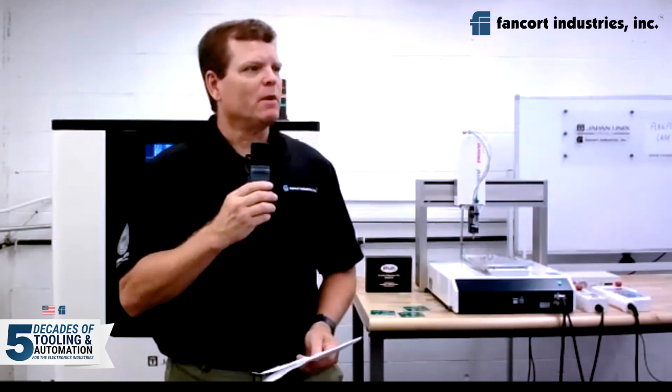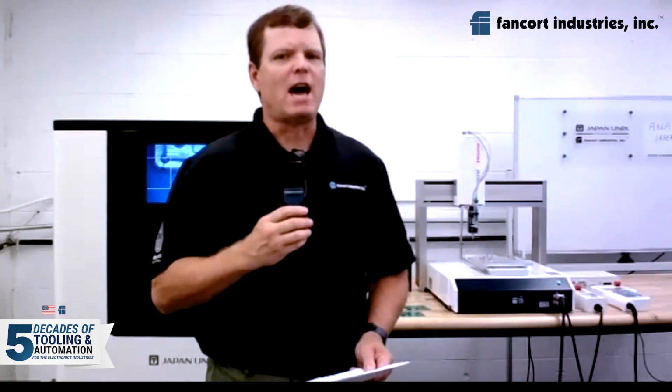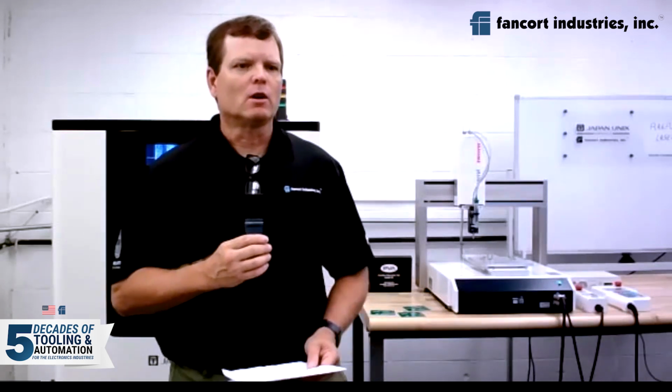Yes, the equipment you're asking about, PTH, through-hole components, certainly can be used for that. The only issue that we have to address, and we certainly can for you, is that we have to ensure the laser does not shoot through the via hole where the lead is located, for reasons of not wanting to damage or burn anything possibly underneath.